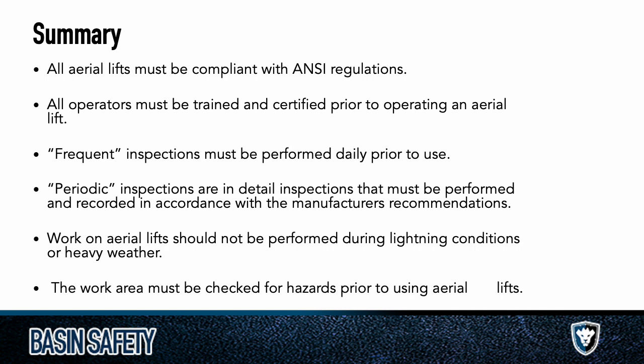Work on aerial lifts should not be performed during lightning conditions, heavy weather, or around power lines. Period. And so we want to make sure that we're checking the work area prior to going to work on our aerial lifts. And that wraps up aerial lift safety training.